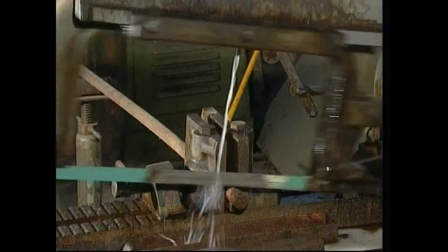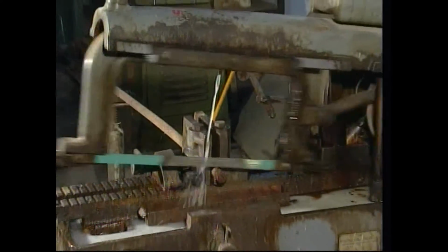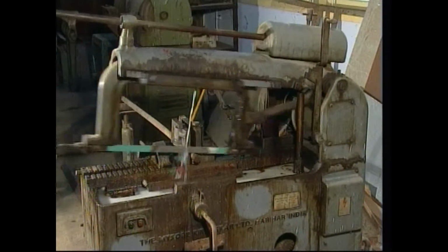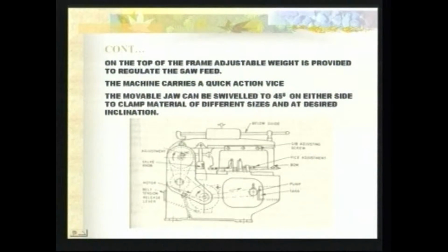While cutting hard materials at slow cutting speed, the use of cutting fluids is not recommended because wet cutting of hard material has a tendency to produce a work hardened surface. Under these conditions, oil should be applied on the blades by means of an oil can to reduce the friction.